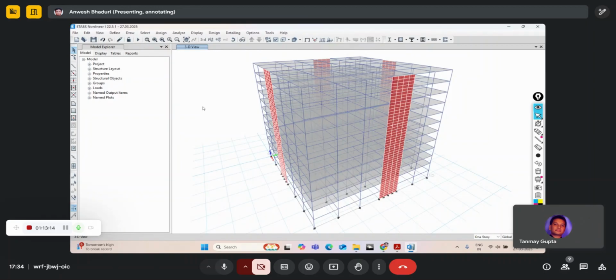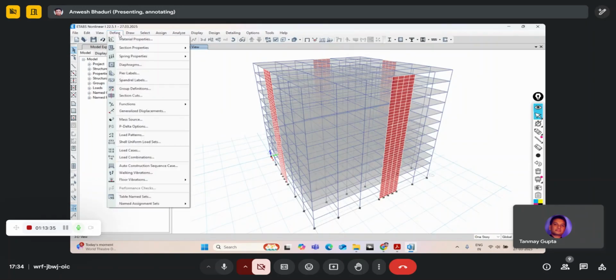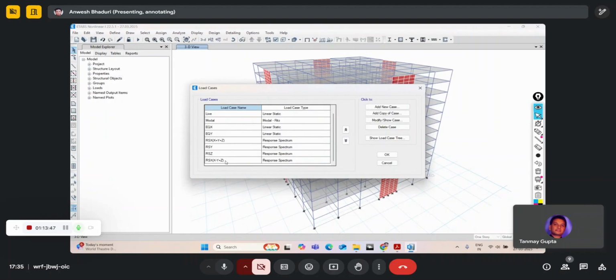I don't think there will be a significant difference in linear analysis between these two solvers, amongst the results, say story drifts or base shears. No, that will not be. The standard solver basically gives a lot of details about where the errors and all are located. So that helps in that case.